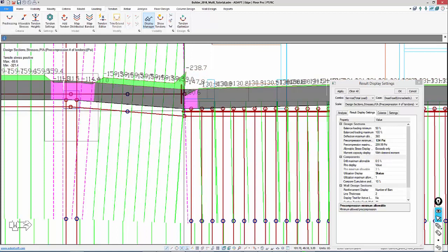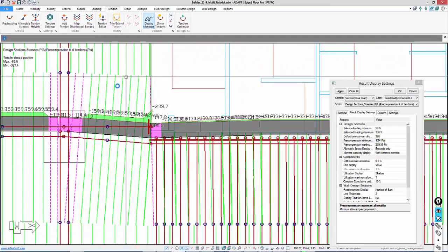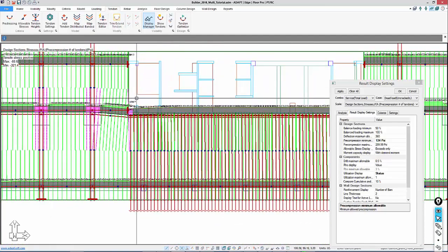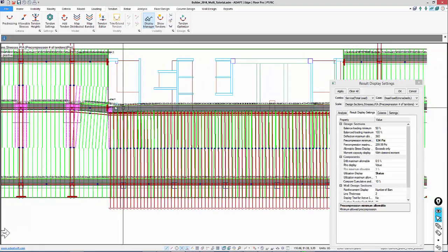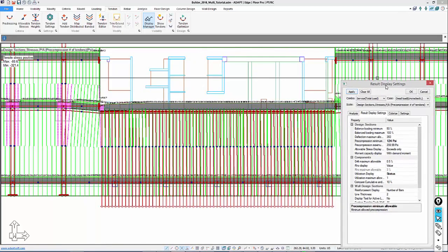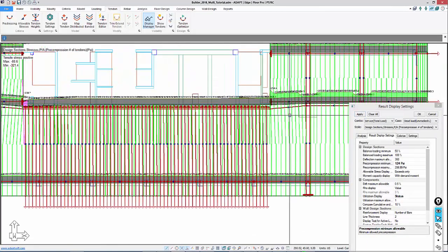We can either solve it by readjusting the section cut or the strip, or by just moving this tendon into this zone so that we feed that area with precompression. One or the other. Physically, whether or not that's possible, that's another story, but from a modeling standpoint, we have to adjust it based on what we believe will be the physical makeup and the physical characteristic of the particular location and situation.